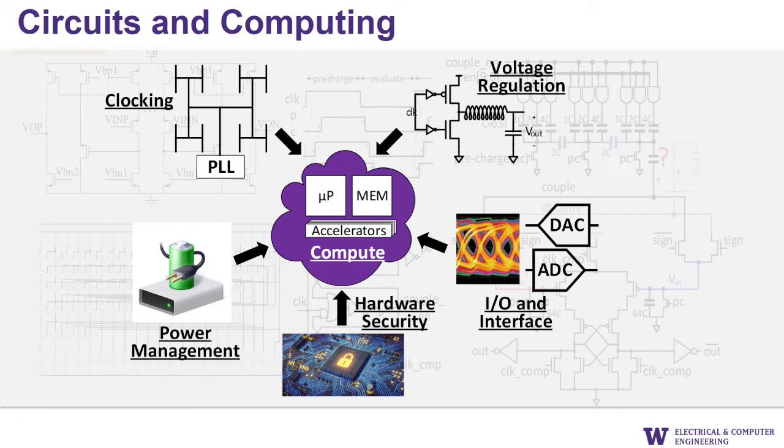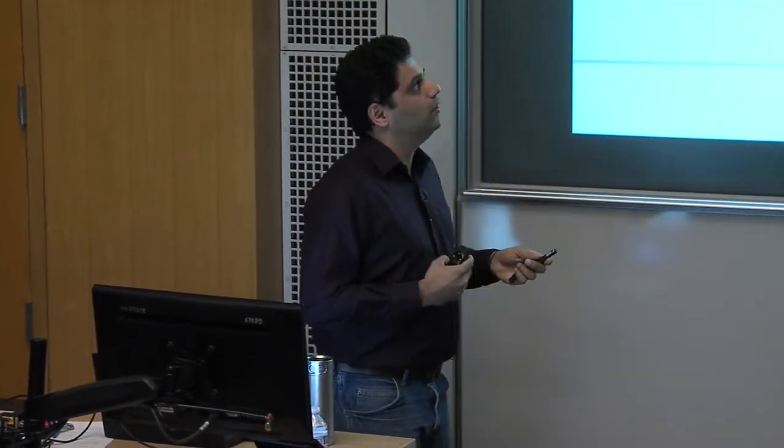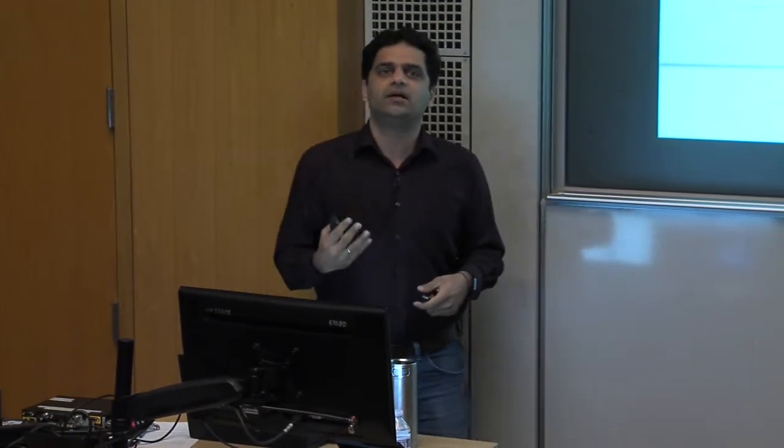You'll have I/O, which is required to connect to memory, connect to other compute nodes. You'll have voltage regulation to be able to target a certain digital system at a given voltage. Power management to orchestrate the power and performance levels of various subsystems in your overall compute solution. You'll have clocking to synchronize and basically time your overall system. And more recently, there's been a need for hardware security to maintain privacy in terms of data that's exchanged between machines. Now, all of these systems and more tend to be very circuit design intensive.